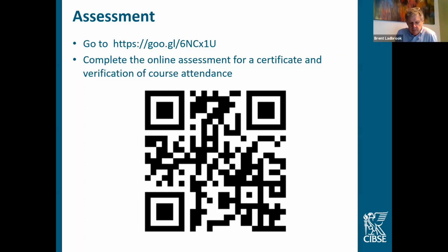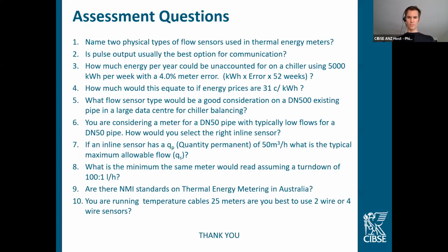Sure. Another one that's just come through, I'm just racking my brain as to the application in building services, but what about fluids other than water, for example, refrigerants or chemicals? So yes, they're quite possible. Certainly with a clamp-on meter, that is quite possible to do. You just program the meter to what it is. It might be a glycol mixture. We don't typically see that in Australia, but there would be parts of the world where that is used. And you can program that.